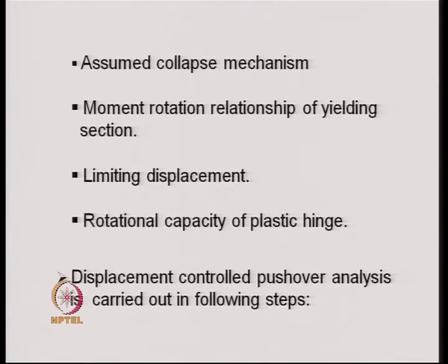Once we say that a particular plastic hinge has exceeded the permissible rotation, we mark that cross section and say that it has completely failed, although the structure has not collapsed completely.